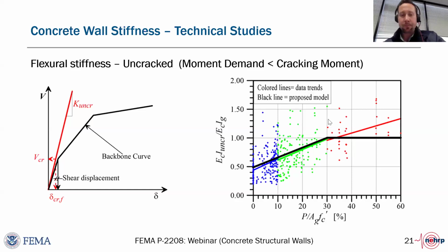And you don't have to. It's always permitted to use the cracked stiffness modifiers because you're going to be conservative on the displacement side, but this gives you a recommendation if you want to capture the increased stiffness for uncracked walls. And this is how we do that.